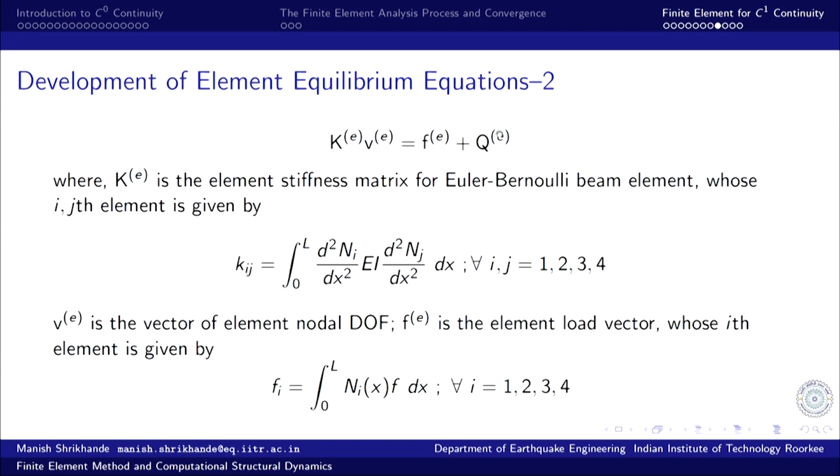So, this is imposing the natural boundary condition. If there is any secondary variable that has been prescribed, we place a node at that particular point where the point loads are prescribed, and the secondary variables are defined appropriately in the element level equations, and then it is taken up for the assembly.